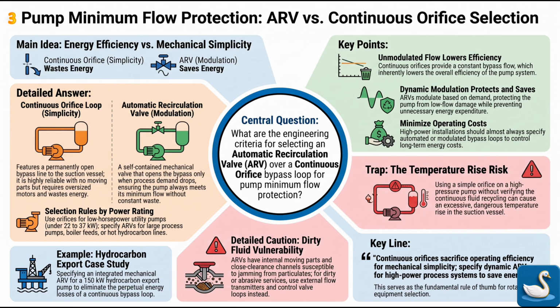Because this bypass is permanently open, both the pump hydraulics and the electrical motor must be permanently oversized to account for the main process demand, plus the continuous bypass flow. Wasting energy. Exactly. This wastes a massive, continuous amount of electrical energy over the entire lifespan of the facility.